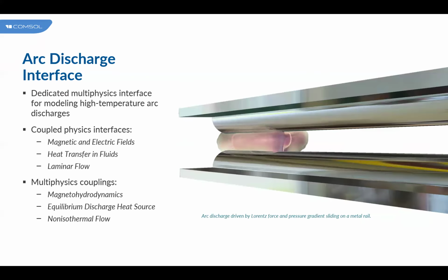The electric discharge module also includes a dedicated arc discharge interface, or rather multiphysics interface. It would be useful if we were to simulate the dynamics of an arc discharge under the assumption that the initial channel has been heated up and the arcs have formed. Here we treat the system as a conductive fluid via the magnetohydrodynamics approach. That said, we are going to deal with the system under local thermal equilibrium conditions.